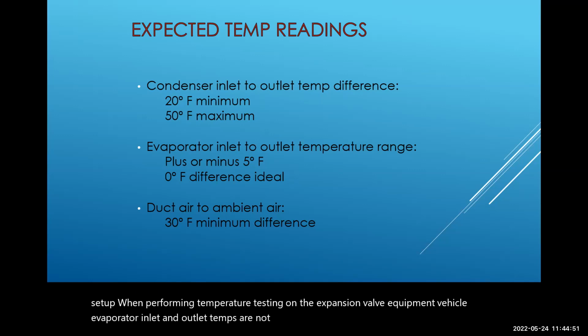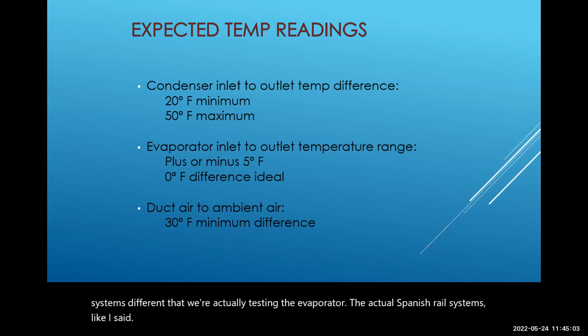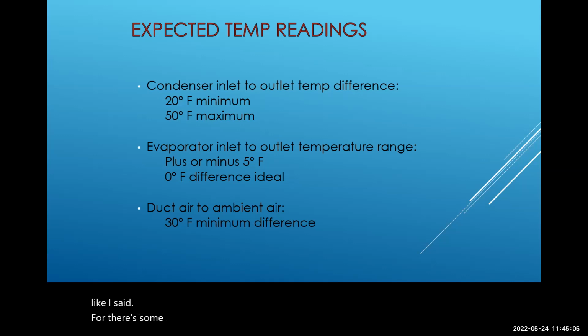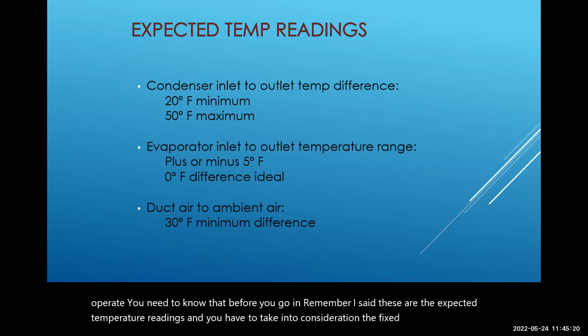So we're checking the fixed orifice systems differently than we're testing the actual expansion valve systems. Like I said before, there is a difference between the two systems and how they operate. You need to know that before you go in. Remember, I said these are the expected temperature readings, and you have to take into consideration the fixed orifice difference from the expansion valve systems.